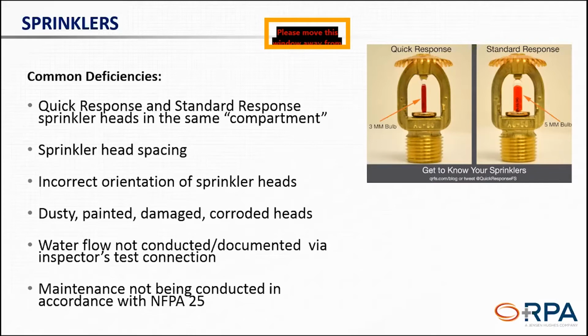And plus, if you have standard response heads throughout your area or a given part of the building, and maybe that head gets damaged or it starts to leak and you're going to replace it, make sure you're replacing it with the appropriate response type. Where we see these become mixed is they grab whatever head they had available and they plug it in there. It stops the leak, but now perhaps we have a mixed head situation in that area.